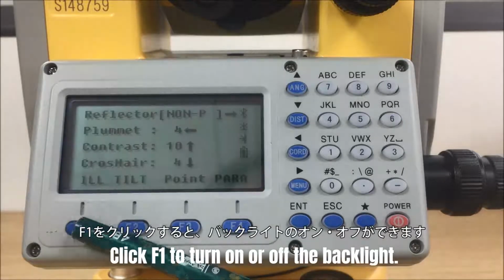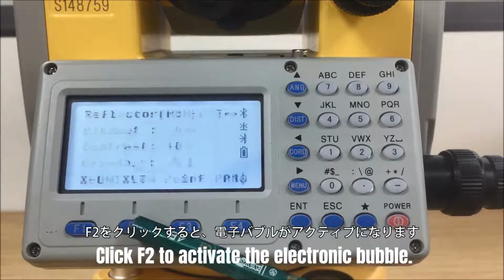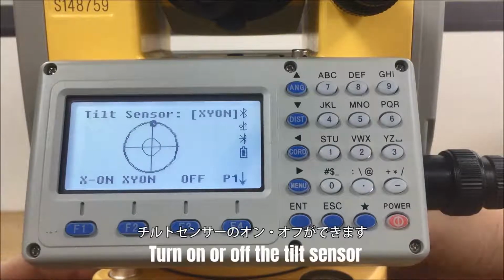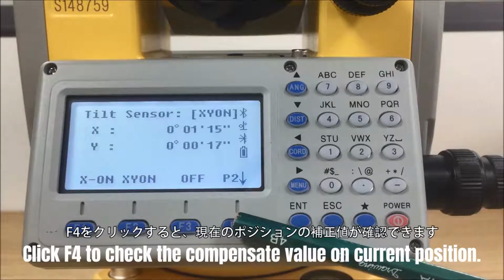Click F1 to turn on or off the backlight. Click F2 to activate the electronic bubble. When setting up the total station, the electronic bubble is a useful tool. Turn on or off the tilt sensor. Click F4 to check the compensate value on the current position.